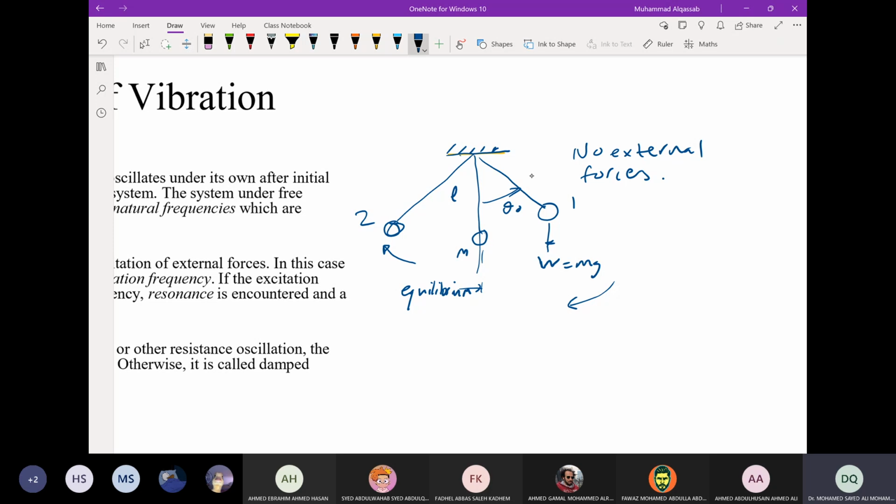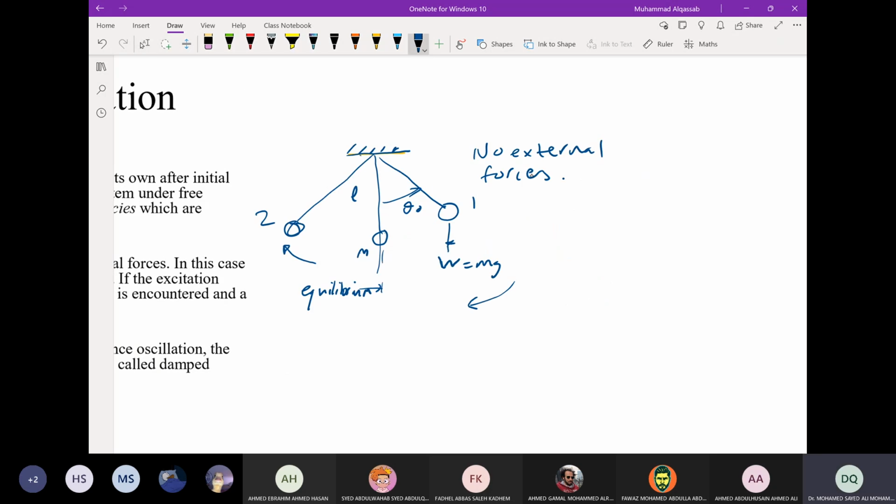There is no damping, but in the negative part. So it goes from plus to 0 to minus, and then it will go back to the equilibrium and then pass it to point 1. So it will oscillate. The oscillations occur at a frequency, and that oscillation will occur at a frequency called the natural frequency.